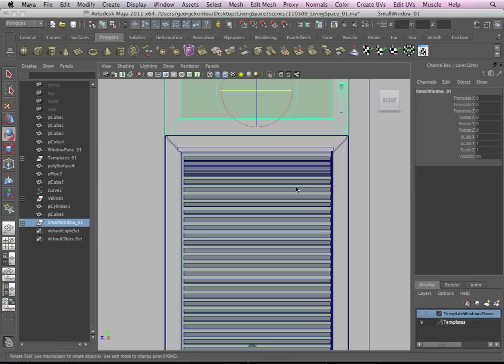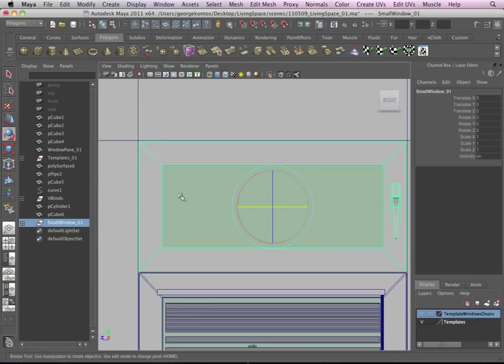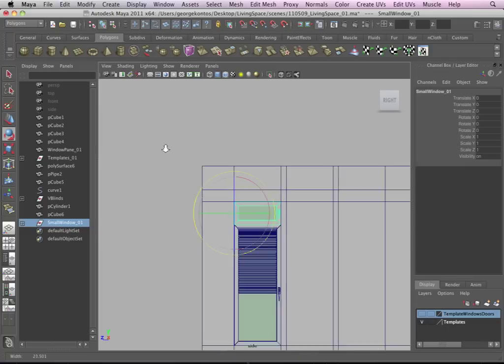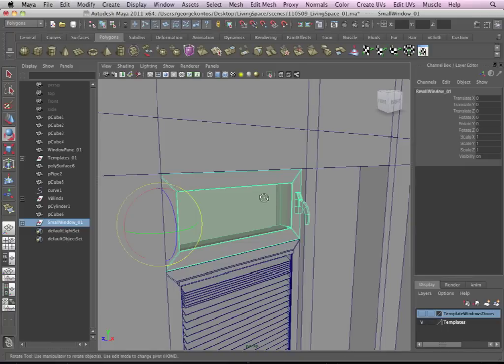So let's go to the side view. The pivot point should be over here where the window hinges on the wall. So I hold down the D key. Holding down the D key enables pivot manipulation. I have a video already that shows that. Moving the pivot point all the way to the edge here. That's the pivot of the group.